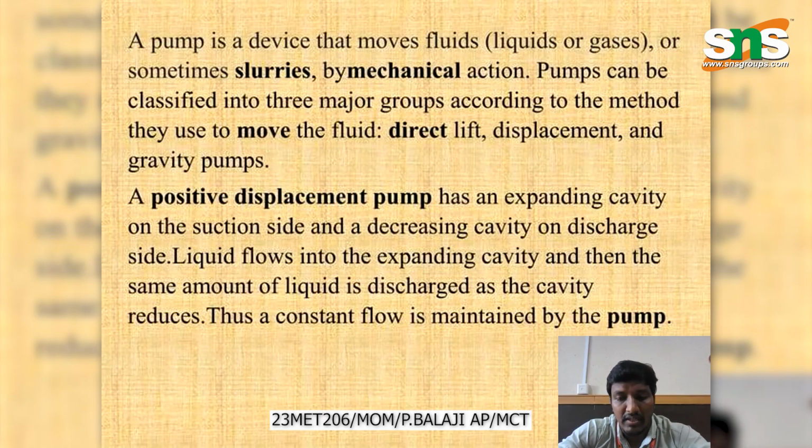A pump is a mechanical device used to move fluids such as liquids, gases, and solids, the latter only for the positive displacement pump. Based on the working principle, it can be categorized into direct lift pumps, displacement pumps, and gravity pumps. In hydraulic systems, mostly positive displacement pumps are used.